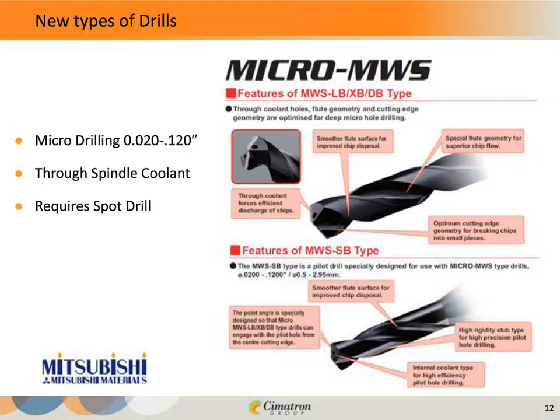And the other thing that I've found out in my research is that, and again, I'm going to speak in generalities, I know that there was not always a black and white when it comes to some of these applications, but generally speaking, if you're going to be drilling with a drill that's under 100 thousandths, probably you should be considering using a spot drill. And then I think over 1/8 of an inch, depending on what length the drill is, probably maybe you don't need a spot drill. But again, I highly recommend you consult your tooling vendor. But I'm going to show you some differences here on the next page.